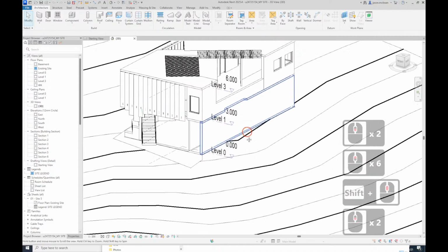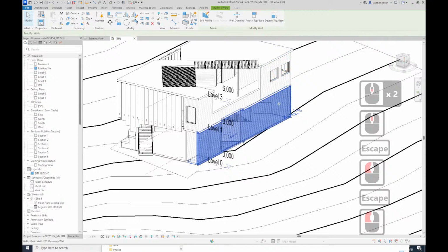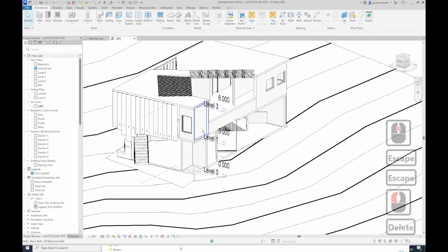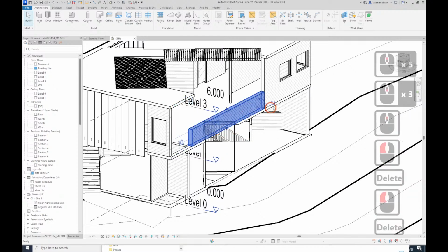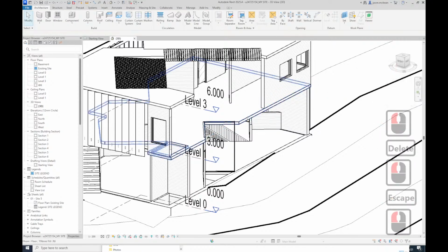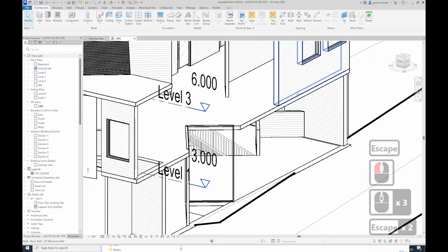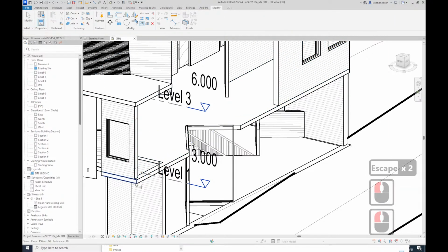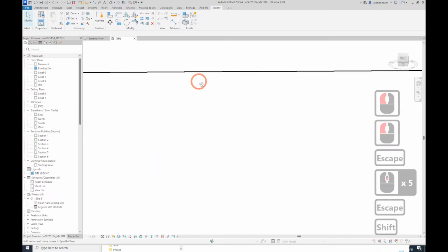Typically, if you're going to take a wall, if it goes from ground, we actually take it up past. So I know we're going to have some issues here. That doesn't have an opening, so what I'm going to do is these all must be one wall as well. But what about the openings? I'll explain. You can actually do this in 3D quite easily. So I'm going to trim single. Select this one. I'll explain, it's actually very easy. I'm going to pull this to there. I know there's an opening there, but we can make it go past that.